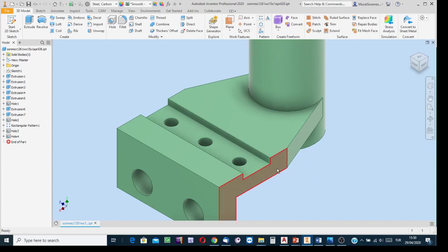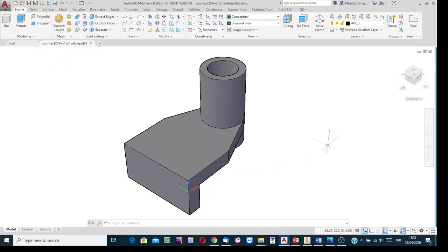On this side surface, take a sketch right in Inventor, but in AutoCAD, bring the coordinate frame onto this surface, XY plane onto this surface, and on the surface draw the edges of the selected surfaces. To have a closed region, between this point and that point you need one more line. After having the rectangle, it is going to be the region. Apply the extrusion process.